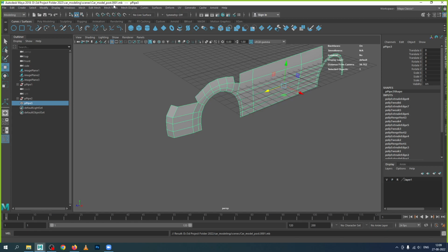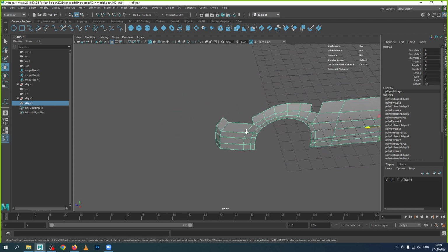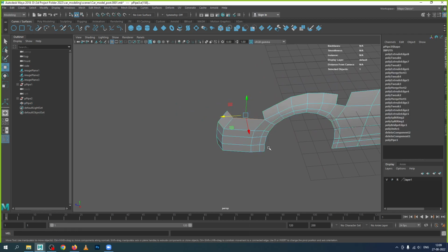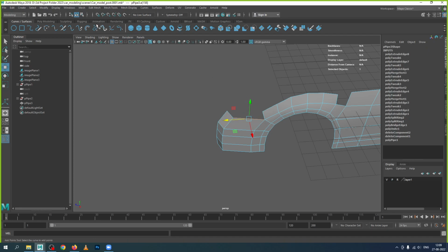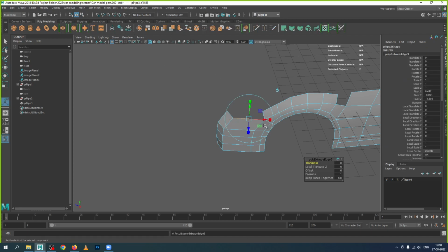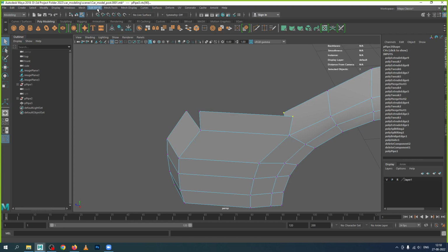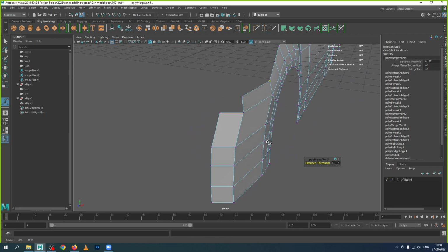Second time, if I have done any modification in this one, for example, I'll select this edge, these 2 edges, otherwise only a single edge, and I'll use the extrude option in this one, poly model, extrude, and try to move up a little bit. Right click on this one, vertexes, select these 2 vertexes and merge it now. Edit mesh, merge in this one now. Okay, properly we need to match it here now.